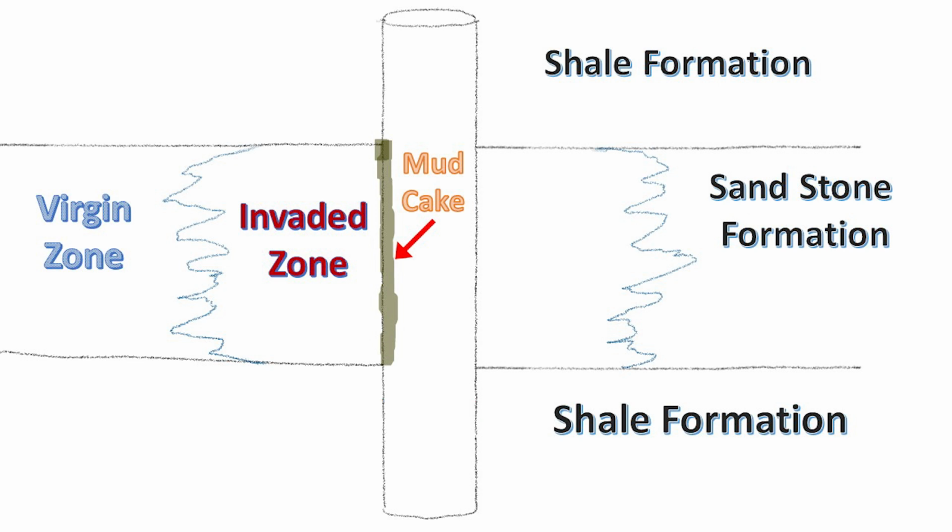To control water loss during drilling, various techniques are employed, such as the use of additives and viscosifiers to improve fluid properties, optimizing mud weight and rheology, and implementing appropriate drilling practices to minimize fluid invasion into the formation. These measures help ensure successful drilling operations while minimizing risks and maximizing well productivity.